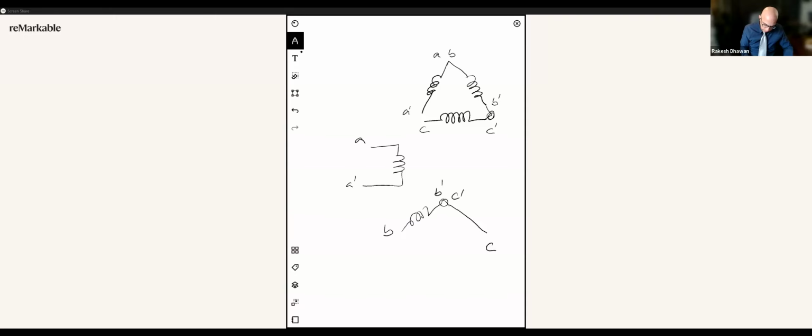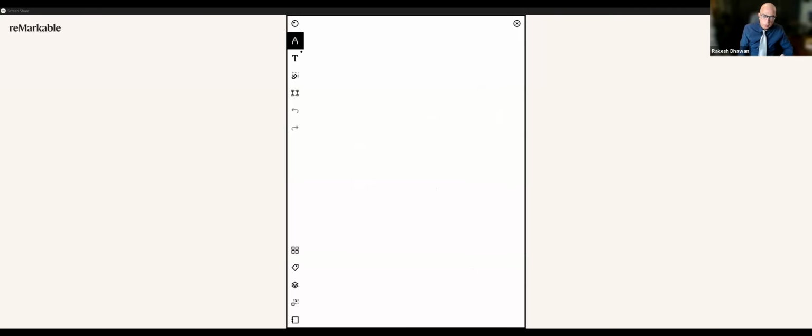B and C dash, okay. So this can work, and you could put a variable resistor here, so this can possibly work to determine LD and LQ values. But your LD and LQ values here are going to be different, right? So effectively, you can use the same technique, but your LD and LQ values compared to Y configuration obviously are going to be different.